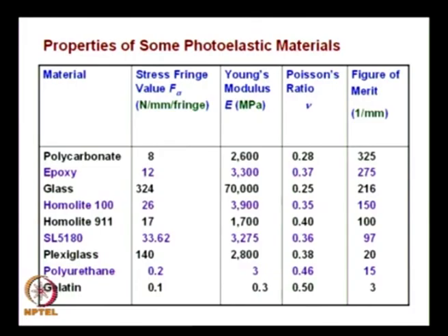So, this gives you an idea of what are the various photoelastic materials, and what we have seen in the class today was, we looked at the importance of color code. We said the color code sequence is advantageous to calibrate the polariscope, to find out the maximum or minimum principal stress direction, and also to find out the sign of the boundary stresses. We have looked at the nail test, we have also looked at how to find out the sign by an external member. Then we moved on to model to prototype relations.